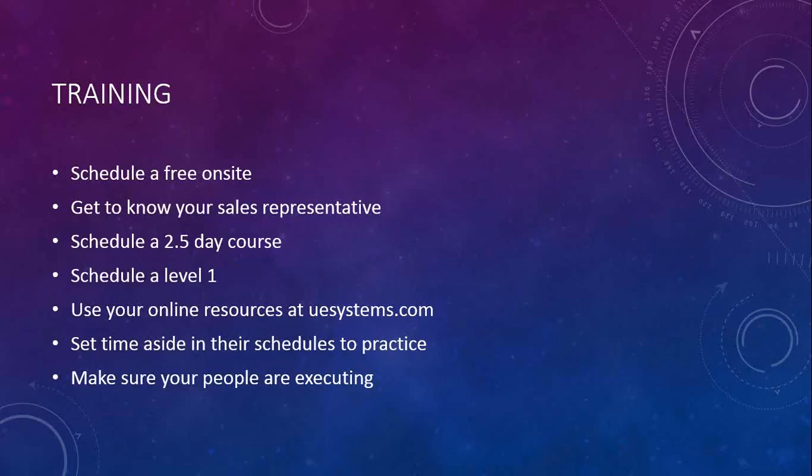One of the things that I do is I make my guys take a before and after photograph with the UE gun, the 15,000 probe, showing the decibel reading after they fix a leak, hopefully at 0, but it depends on where the leak is and if there's other turbulence around the gun. But that, 1, it covers you and the fact that you fixed it, and it shows that it's fixed. And 2, it covers the technician, showing that they've executed the work, as well as putting the work orders in the system and tracking that.